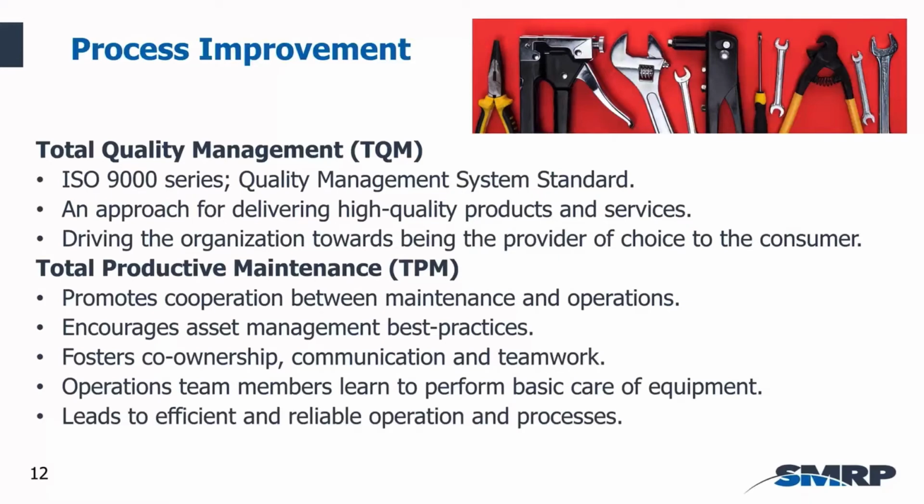It leads to efficient and reliable operation and processes. And the ultimate goal is to have no breakdowns and no accidents. And again, with total productive maintenance, when the operations team can take over some basic equipment care functions, it frees up the maintenance personnel to do higher level or more planned maintenance activities.